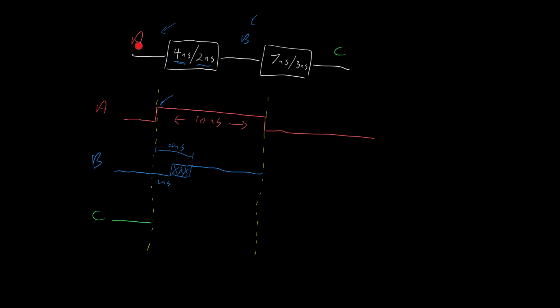So, provided the inputs vary sufficiently slowly and we've waited long enough, logic circuits are fully described by their truth table. That's what we learnt in part 1 of this course. But during the time when the input first changes and the output settles down, we can have a transient response, and in our timing abstraction, we simplify it to a period when the output has not yet changed, a period when the output is correct, and in between we don't know and we don't care. We can build digital circuits without knowing or caring what's happening in this region in here.